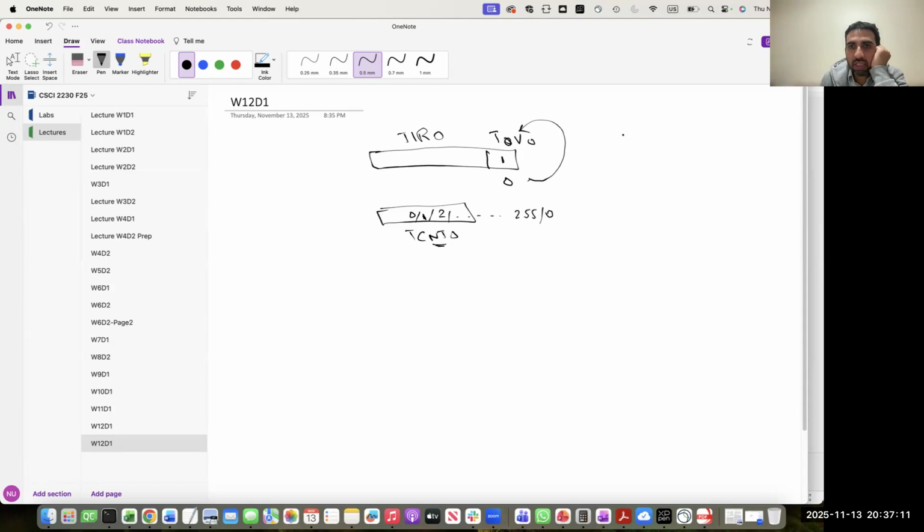It means that for 255 times when the microcontroller checked the flag, it found that the flag was not set, and on the 256th time, it found that the flag was set. And then it can continue with the rest of the program.